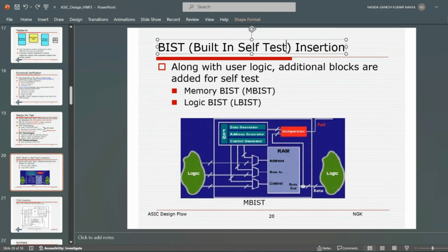You just trigger it, you enable the BIST from the board level. Board level means directly your IC. You just give the BIST enable signal, enable it once, done. It will automatically test the internal logic and give you the output. So you don't need to go inside and do all this testing. Let's say your mobile phone or a laptop or any electronic gadget can be tested by the manufacturer or a technician. You go to the person and say that my mobile phone is heating up, or it's blank, it's not working, and you want him to check.